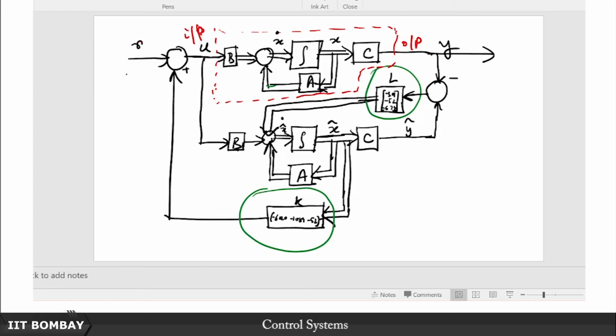So after root locus we delved into this idea of Bode plots, right, frequency response, where we saw the phase and the magnitude plots of the system, and from there we understood the meanings of certain terms like bandwidth, phase margin, gain margin, resonant frequency, many of these things we understood. Gain crossover frequency, phase crossover frequency, we saw them pretty distinctly and clearly. We also realized why certain systems are called non-minimum phase when they have right half plane zeros, that was very transparently apparent when we looked at the Bode plot of such systems, right. What was non-minimum about the phase in such a case, that is what we actually saw, right.